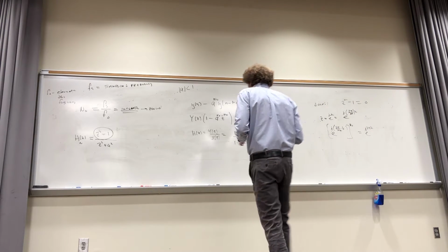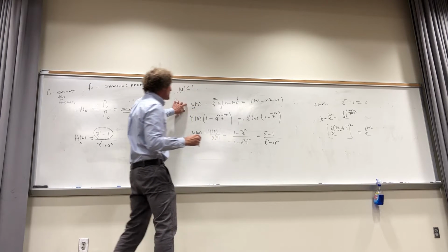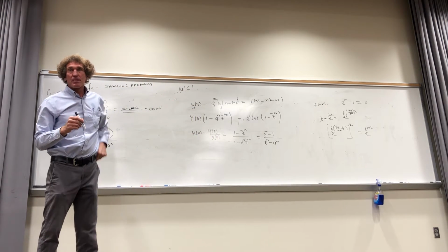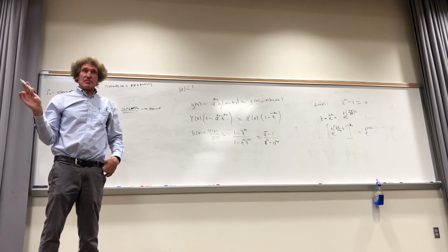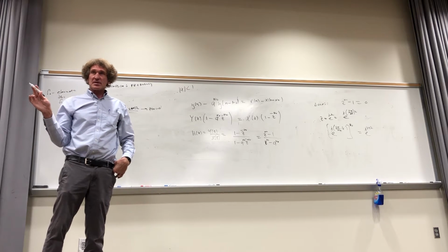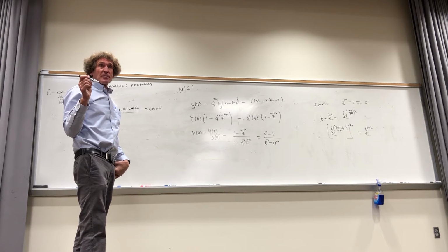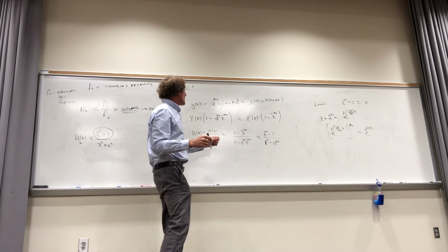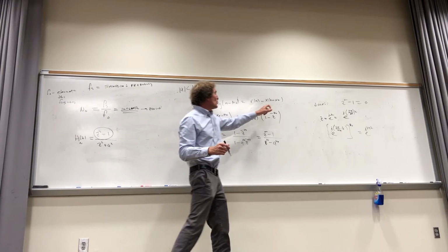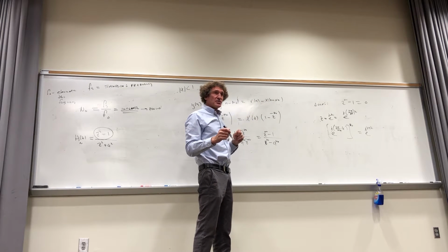Now, what about this filter right here? How many terms do I have there to keep in memory? N naught is given. Follow me? If you have a signal and you're sampling at a certain rate, and you know the frequency you want to get rid of and any harmonics, well, here I only have what? 1, 2 memory items plus an input. Do you see what I'm talking about?